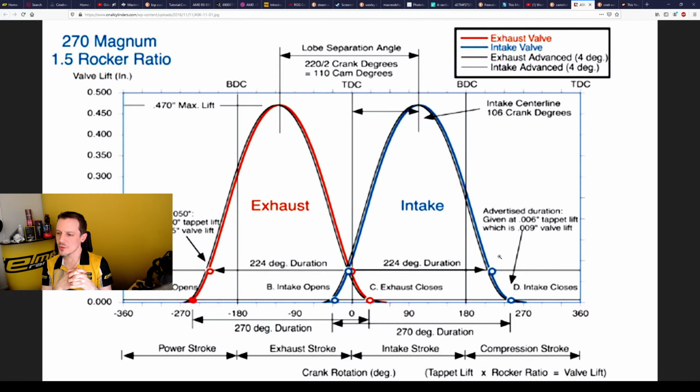That's actually kind of interesting. So what's actually dampening the closing part then? I'm guessing they probably have a hydraulic damper there. So use air pressure to open the valve, and then another air pressure section to close the valve, and then have a hydraulic system to dampen that movement and slow it down. Because if you're just closing the valve with air pressure and just slamming it closed, then that's going to destroy your valve train very quickly. So I'm assuming they have a damper on the closing section also.